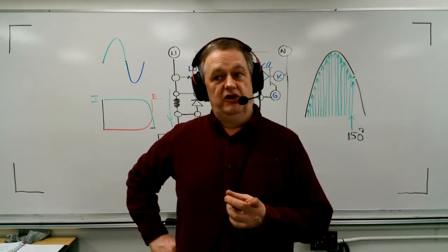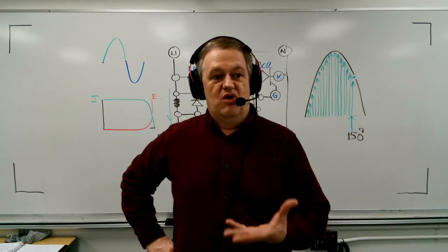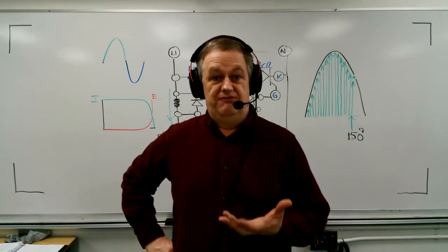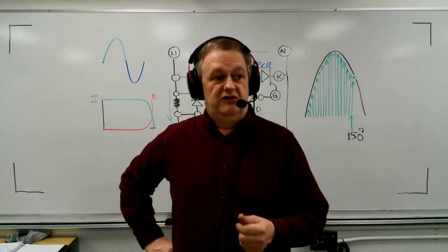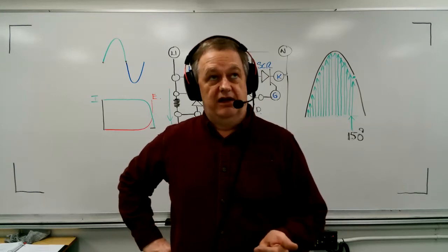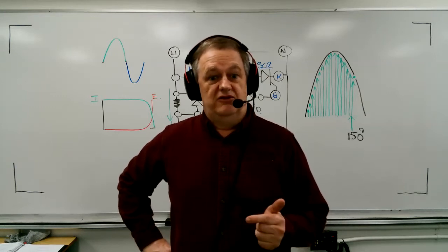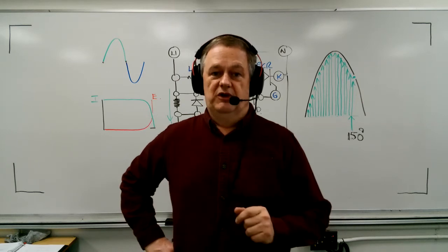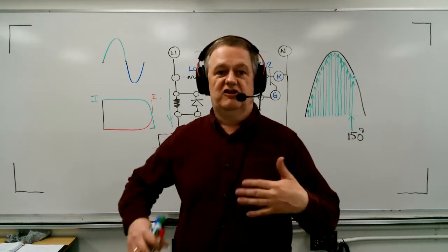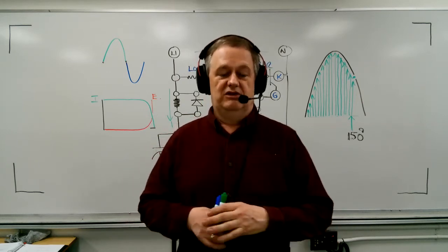Adding a capacitor means that I have more current that I have to fill up before I get my trigger pulse. So that means I'm going to have a later firing angle. So that means less load voltage. Okay, so that's the way we have to be able to think of it. It's just more and less kind of relationships.